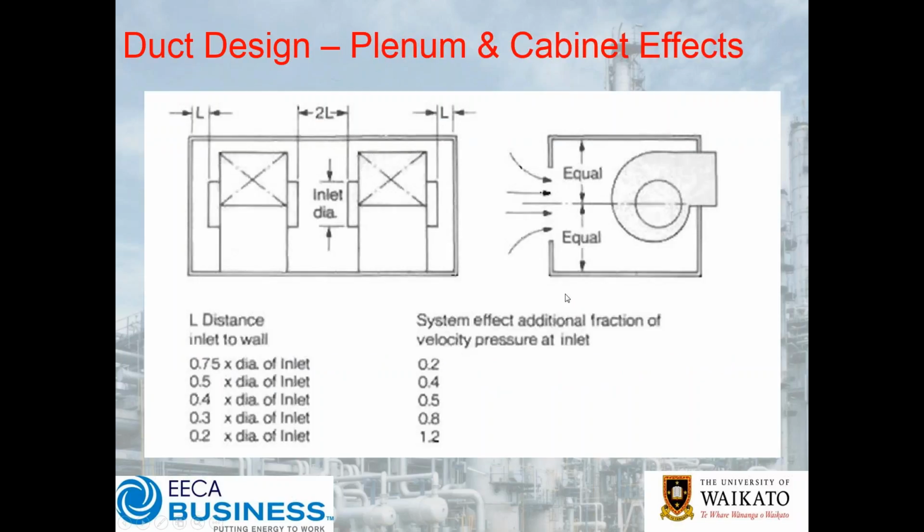Now another common problem that we see is where you have multiple fans together in a room, and you might have inlets that are opposite one another. As a general rule of thumb, and once again there are a lot of design engineers out there that either A, don't know, or B, haven't taken the opportunity to avail themselves of what they should do. But so that you know, and so you can point these things out, know to ask the right questions. If you have two opposing inlets into two fans, as an absolute minimum you want 2 diameters separation between the two.